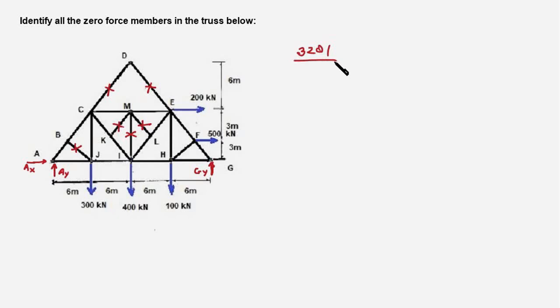but as I practiced more and more problems, I began to look for a visual pattern like T. So this would represent the collinear members, and this would represent the third member and no external force on this T. So I would look for this pattern in the truss.